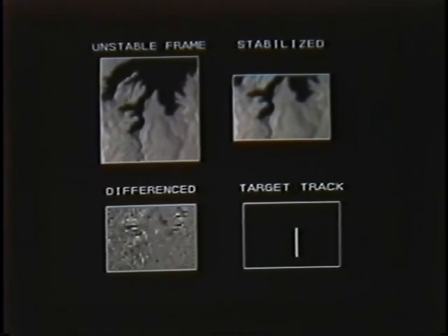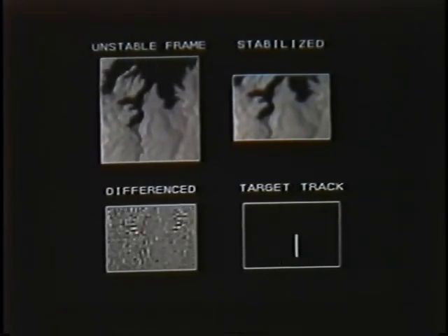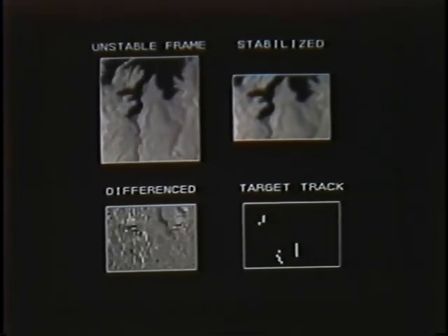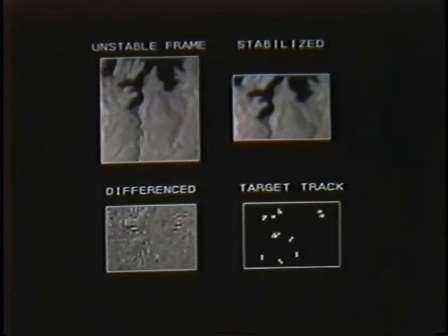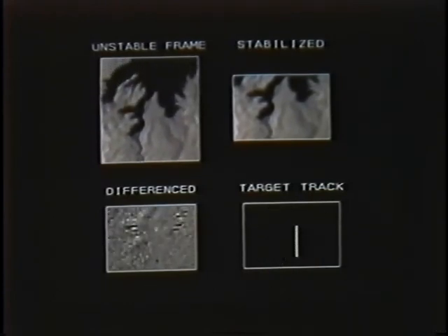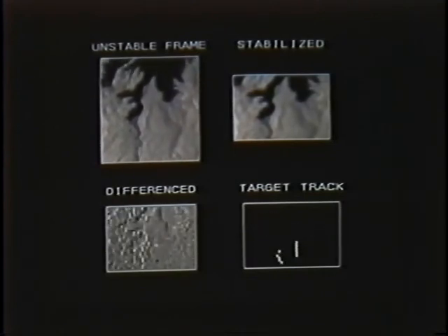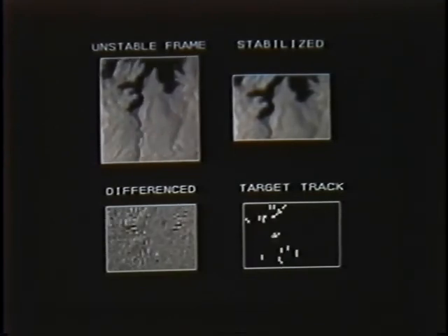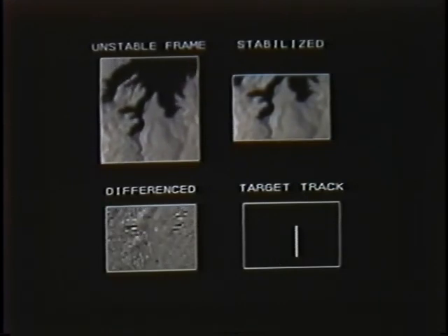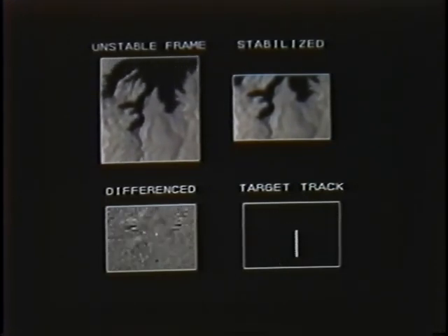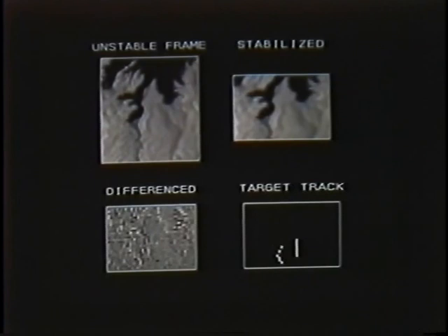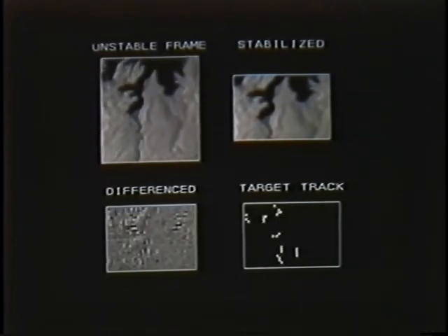As a result, the target appears to be motionless in the frames, while the background moves by. Even strong targets are difficult to detect in sequences such as this, since the target cancels out with itself in the difference. In other words, if the target is in the same position in 2 frames, it subtracts to 0. That's what we want the background to do, not the target.